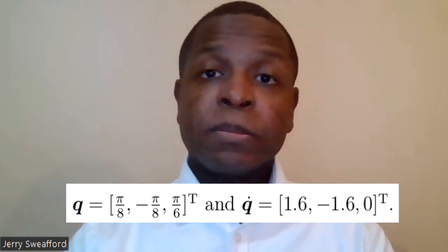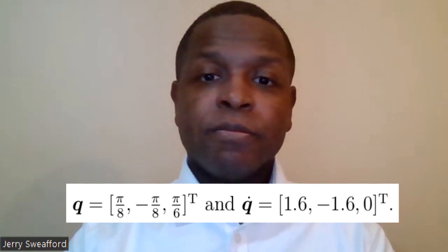Finally, to ensure that the controller will produce periodic behavior, that is, a consistent walking pattern for the robot, initial conditions for limit cycles must be tested. We found a stable limit cycle for the following set of initial conditions. With a stable limit cycle found, we expect to apply the designed controller to the hybrid model and achieve periodic stable walking behavior.